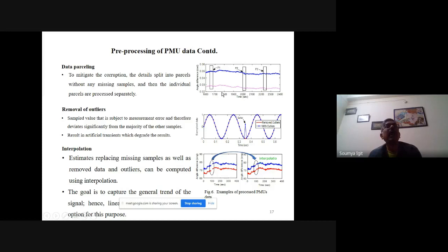That means you are taking different signals from the PMU, for instance the rotor angle, the faulted voltage and current at different instants of the fault, and other impulsive transients, notches and possible scenarios in the power network, like capacitor switching. So you are removing the outliers and interpolating the same.